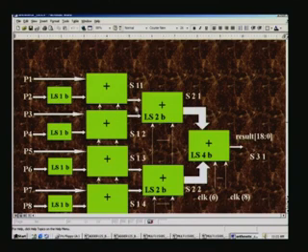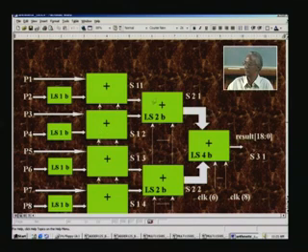I will explain this as the typical case of this new algorithm, and now what we have seen in this previous example is P1 through P8 as being partial products. So, in the Verilog code that we are going to consider, we will see how P1 through P8 are arrived at. For the time being this is sufficient if you just add P1 and P2 to start with, and when you do this we have 4 such adders here which will add 2 numbers at one stroke.